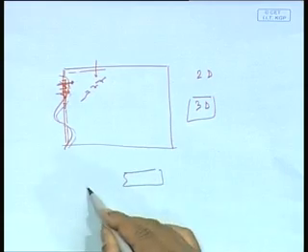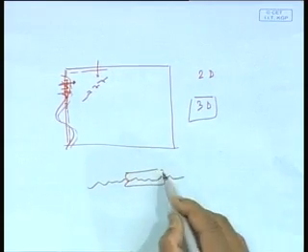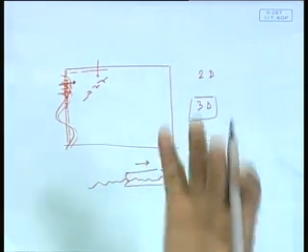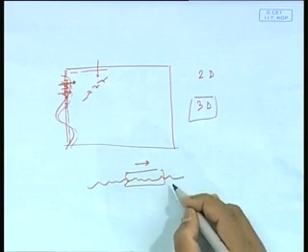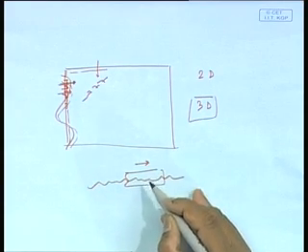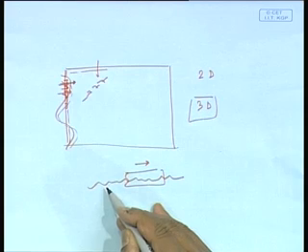As I said, in a 2D spectrum I am presuming all the waves come from one direction. So all are focused in one direction, and suppose I have a ship which responds heavily to waves coming from one direction, then it is going to go up and down much more. Now, for the same ship and the same wave height, if I assume waves come from all directions, the response will be slightly mellowed.